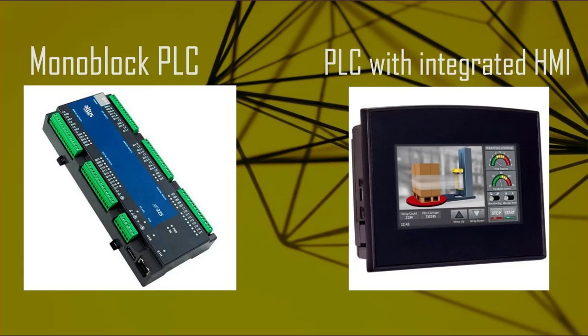Yes, PLCs with Integrated Human-Machine Interfaces, HMI, are becoming increasingly popular in industrial automation. This integration can provide several benefits such as reduced complexity and cost. Integrating the HMI into the PLC reduces the number of components needed in the system, simplifying installation and potentially reducing costs. Improved communication. With the HMI and PLC in the same unit, there is less potential for communication issues or delays between the two components.